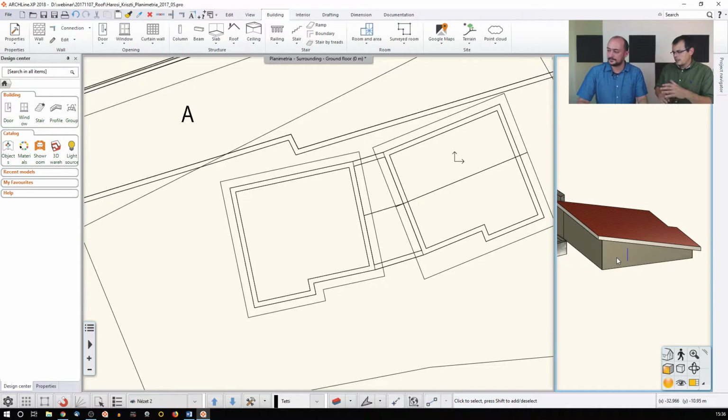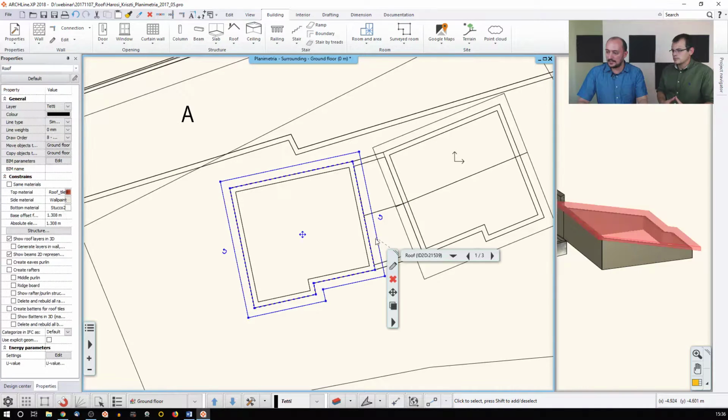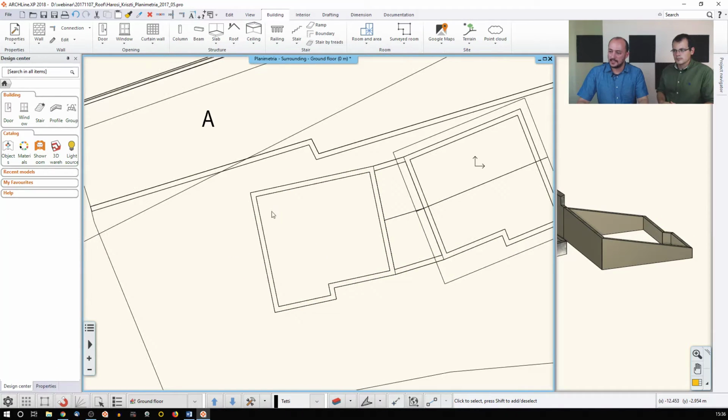If you make up an attic space of several different roof planes, do you have to manually merge them, or does the software do it for you? If you draft roofs plane by plane, you will have to stitch them together manually. Let's see an example of that. Let's say this is a bit more complex, and I could see that there was an edge coming here. Perhaps it was like a 45-degree angle or something like that. Then I can easily draft it here.